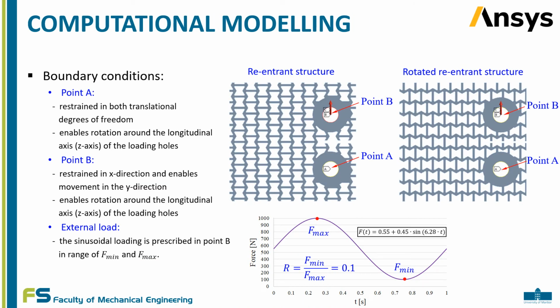Computational modeling. In the presented work, the computational model was built in the ANSYS software package. The boundary conditions were prescribed in the reference points A and B, which are in the center of the clamping holes. In the computational analysis, the external force was defined as one closed sinusoidal loading cycle between the minimum and maximum force, as shown in the figure below.